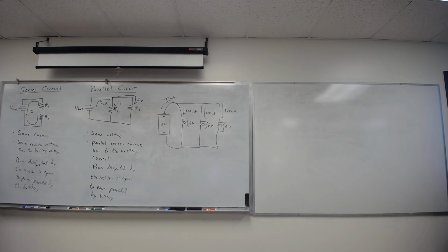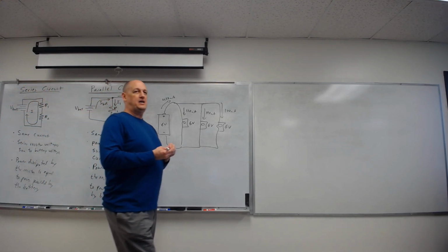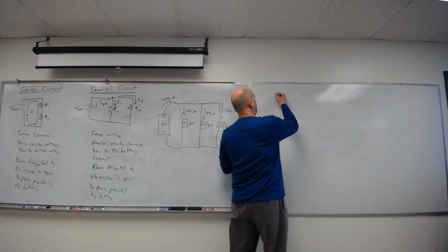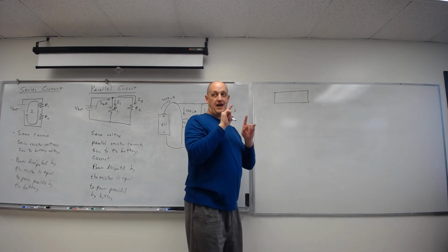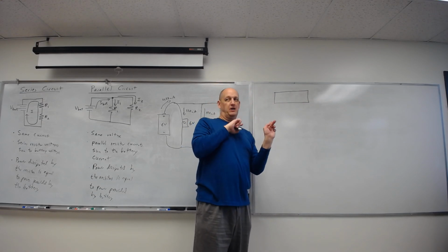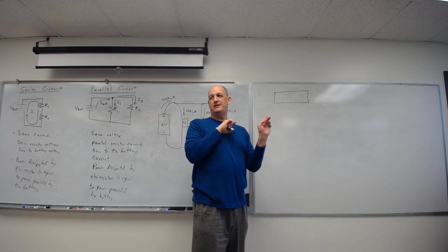After that, I say, get another resistor. So the first resistor I gave you was a 1 kilo ohm. The second resistor I gave you is a 1.5 kilo ohm. And you're going to hook them up. You've got the power supply. You set these up as independent. I believe the lab does have a typo that says set them up parallel. Don't do that. Just set them up independent.